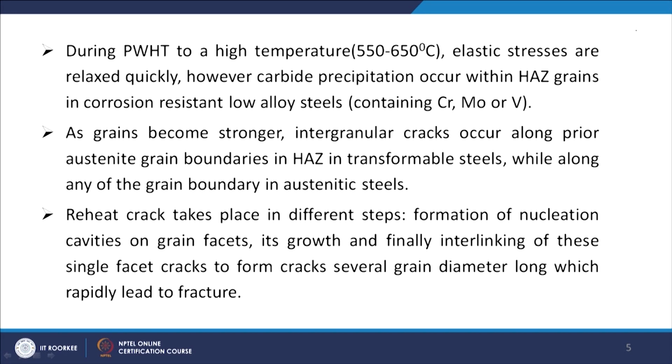They are relaxed quickly, but then carbide precipitation will occur within the HAZ grains in the corrosion and heat resistant low alloy steels, which contain chromium, molybdenum or vanadium as alloying elements. As we know, these alloying elements are strong carbide forming elements, so carbide precipitation can occur when you are doing the stress relieving treatment.